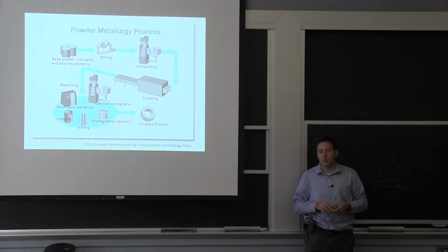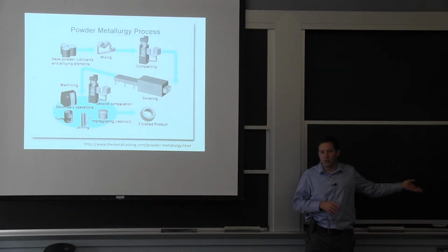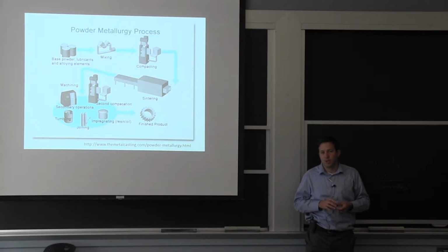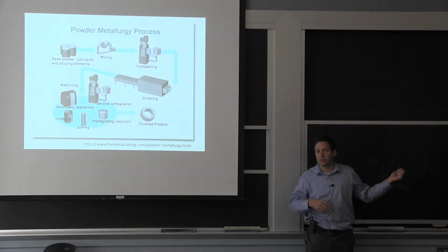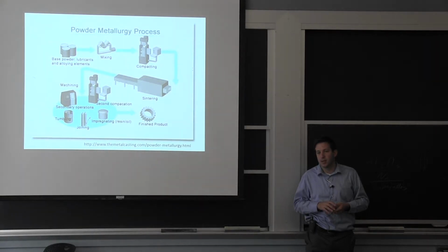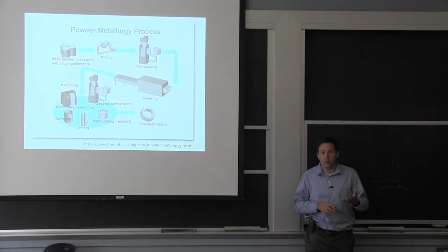Otherwise, typically, when you do the sintering, you move all those grains, and the grains are generally still fine, but more determined by your sintering process. And a good advantage for wear resistance is that when I mix two different powders, I get a two-phase alloy that is more stable to prevent grain growth when I go through these high-temperature sintering processes. So that's why we don't go through deformation processing here to refine our grains, if you remember what we were talking about earlier in the class.